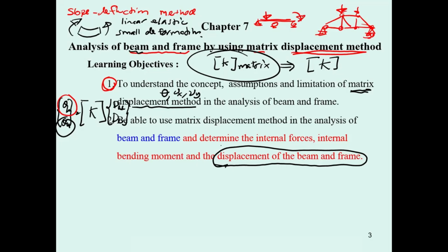That's going to be the main point. Based upon this, the members of the truss have to be two-force members. Again, the members of the beam will not be two-force members. They're going to bend. They're going to be subjected to shear force, and to bending moment.